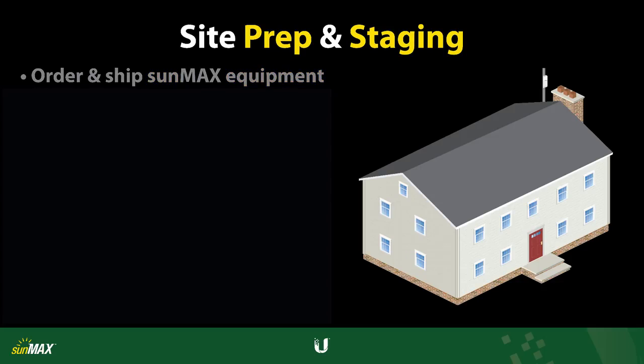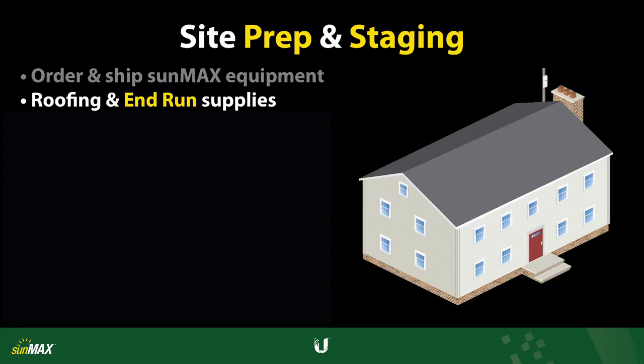Whether working alone or with a contracted electrician, you will also need to purchase supplies for a customized end run to carry electrical wires back to mains AC service equipment. This includes, but is not limited to, conduit, wires, nuts, and overcurrent protection devices, and possibly an AC disconnect, as well as a new main AC service panel, all of which should be rated to the system ampacity.